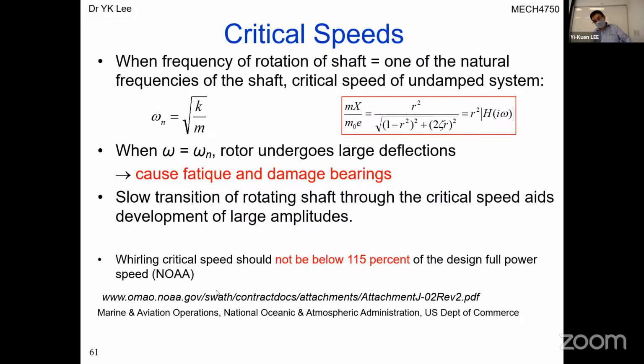I think this guideline can also be used for the Yunzhou Tech project. Remember we have the engine, transmission, and the shaft, and if the shaft is low enough in frequency, we may have a problem from the engine through the shaft to the other end. So in this case, it's important to do this kind of analysis.